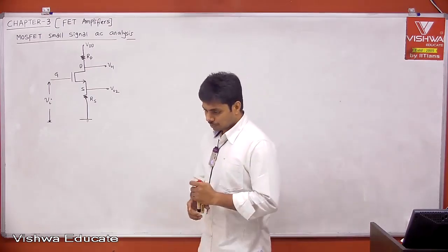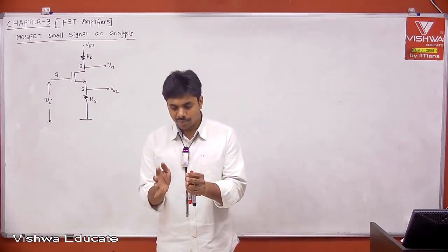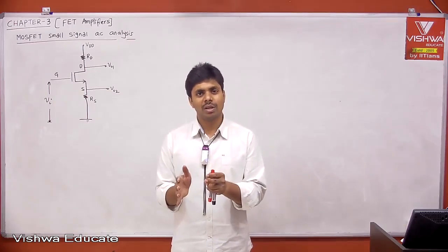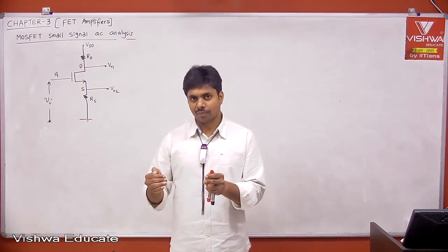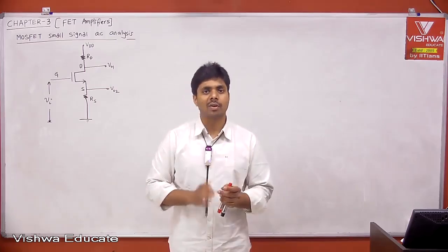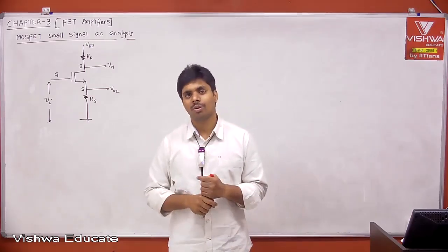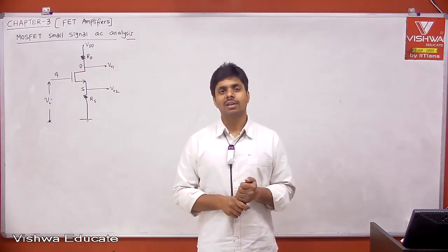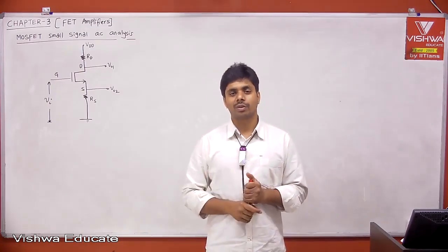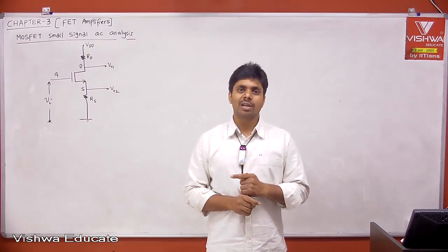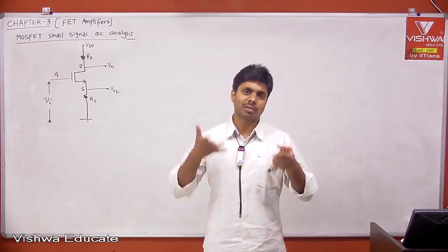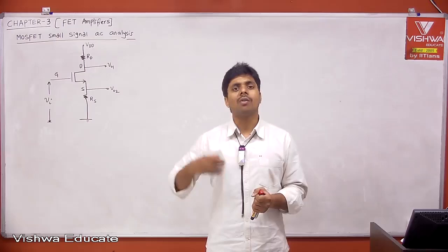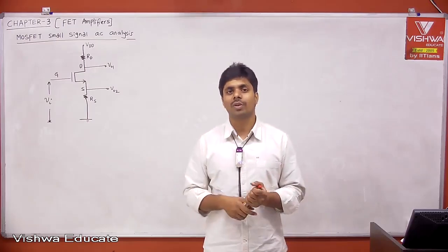Let us say I am taking a black box and I am saying current gain is infinity. When I say current gain is infinity, what does it mean? Whatever current you are pumping, infinite amount of current you get at the output. Is that true? No. Infinite amount of current we are not seeing at the output, right? Here, current gain is not defined. We should not define current gain because it is not doing current amplification. Because input current is 0, it is not even taking any current. Then how can you say there is a current gain? No, we cannot say that.